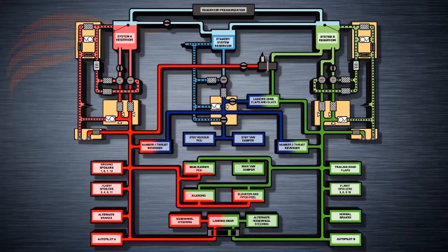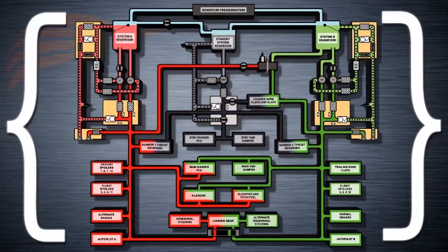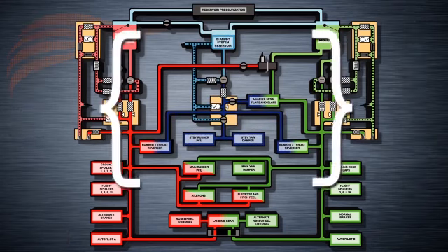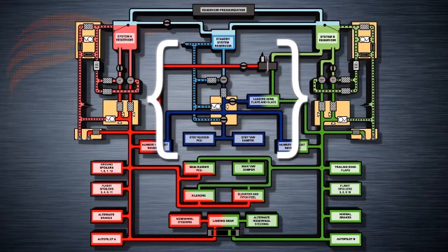There are some pretty vital systems in that list, which is why we have 2 main hydraulic systems. This gives us system redundancy and with that comes greater safety. The standby hydraulic system is a further backup that is available in the event that either system A or B pressure is lost.